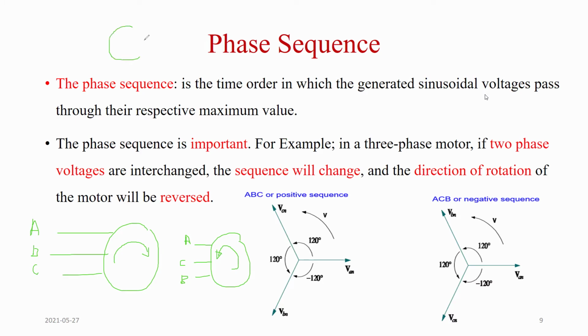And if the same motor has the three wires, and you supply it here with B and A and C here, it's going to rotate in this direction, opposite of this, because this is basically A, C, B. What's after A is the C.